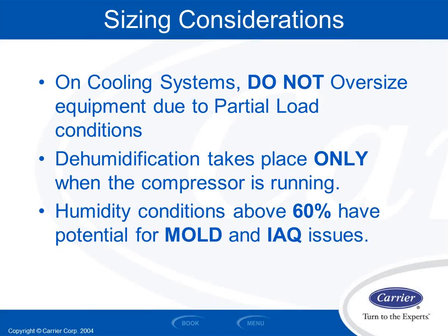And this class is not about oversizing. I have separate classes on that, but it's a pet peeve of mine. But in general, I'd say well over 90% of the equipment you interact with is probably a little bit oversized, if not a lot oversized. The more oversized it is in the cooling scenario, the faster the thermostat's going to get happy, right? And that might sound like a good thing at first until you think about what I just said. If the thermostat gets happy too quick and it meets its set point, say 74 degree temperature in the room, it shuts off the compressor. If it shuts off the compressor before I've dehumidified, I'm going to have a humidification problem in the space.